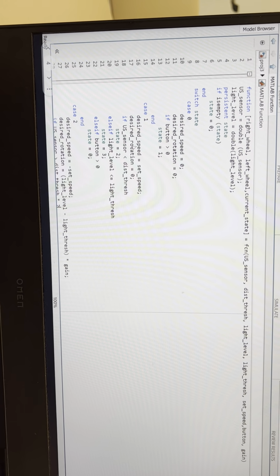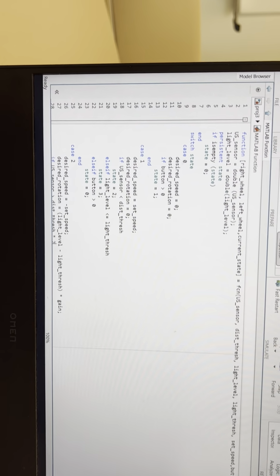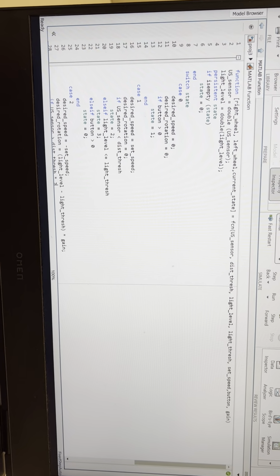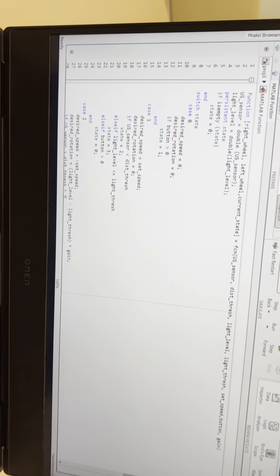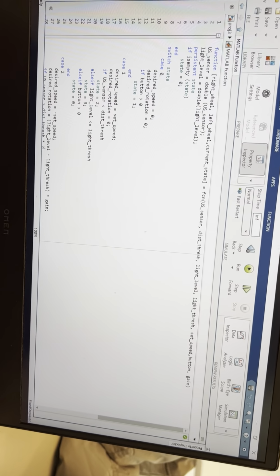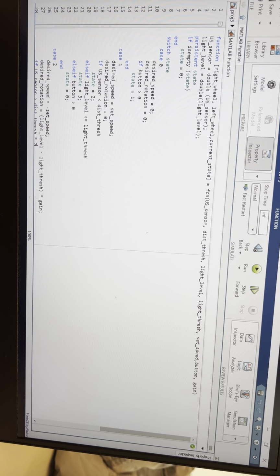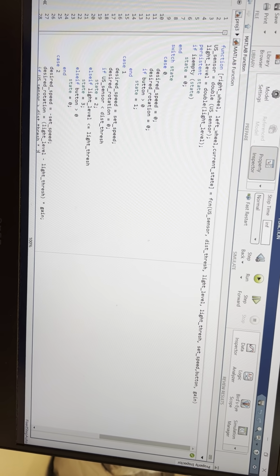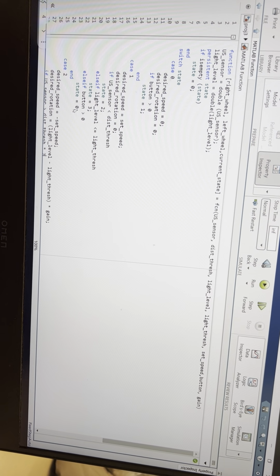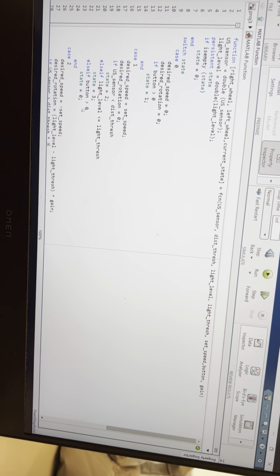During this case, if the ultrasonic sensor detects an object in front of it which is smaller than the distance threshold, it will enter case 2. And if the color sensor detects a light level less than or equal to 12, which is the number that we have calculated, the state would be equal to 3. And the button is just like a safety button so that we can turn off the robot.